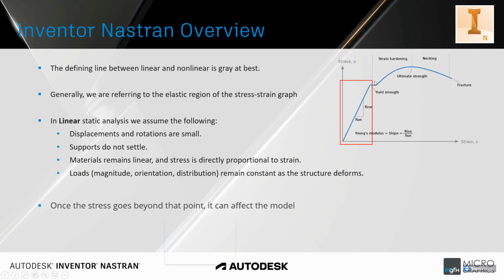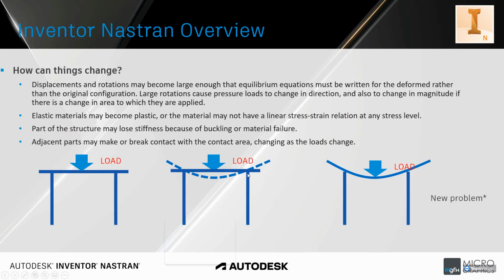However, once you go past the yield strength, you start to go into permanent deformation. And once your deflection becomes really, really large, as shown in our diagram here, you'll find that now you're no longer analyzing 2 uprights and 1 horizontal. You are now analyzing 2 uprights and 1 curved beam. Remember, this curved beam no longer has the same strength as that horizontal beam.